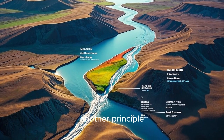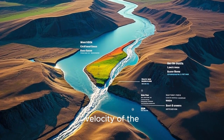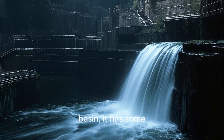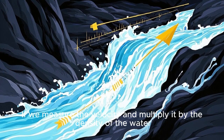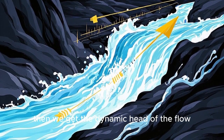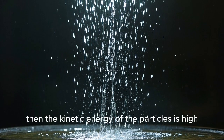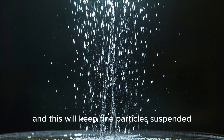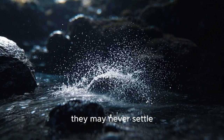But there's also another principle that controls how quickly these particles settle, and that's the velocity of the water entering the basin. As the water approaches the basin, it has some kinetic energy due to its velocity. If we measure the velocity and multiply it by the density of the water, then we get the dynamic head of the flow. So if we have a very high velocity approaching the basin, then the kinetic energy of the particles is high, and this will keep fine particles suspended. And even if we wait a long time, they may never settle.